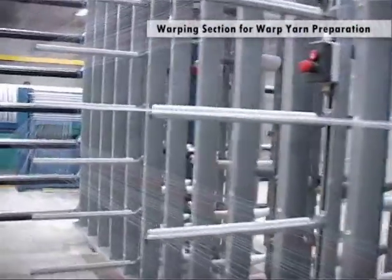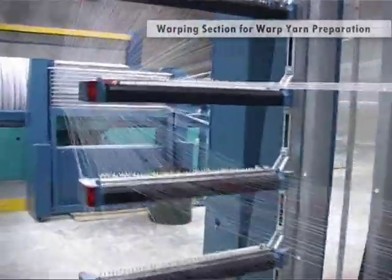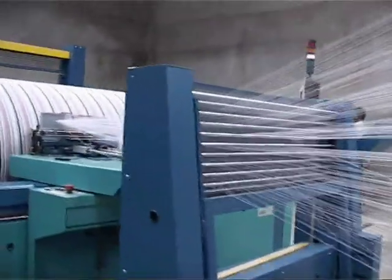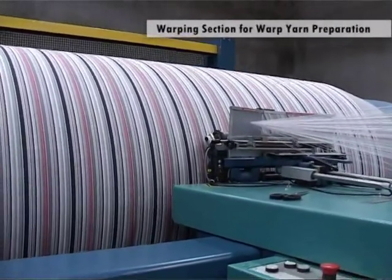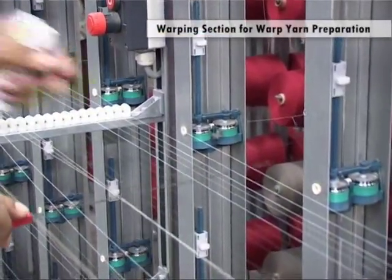Depending on the kind of intermediate carrier used, the industrial warping process can be carried out according to two different technologies: sectional warping, indirect or conical drum or dresser warping; and beam warping or direct warping, preparatory beam warping. Now we focus on the principle of sectional warping.